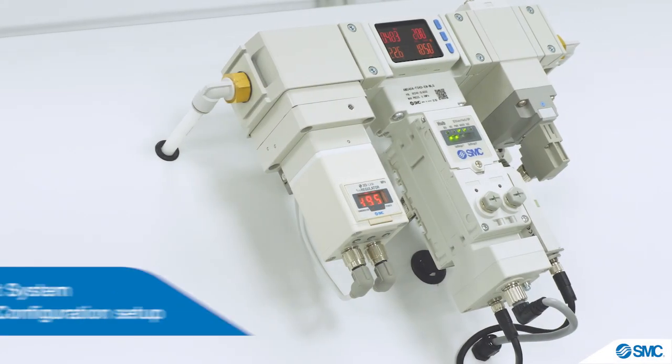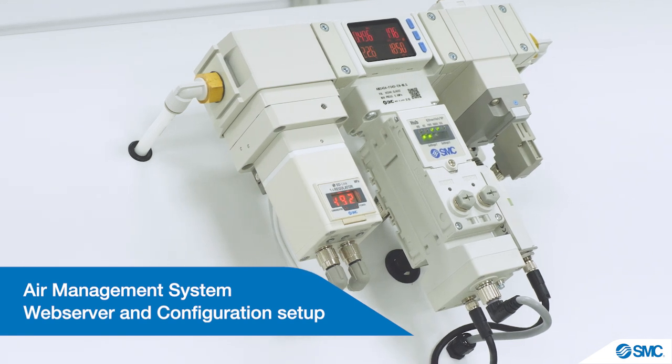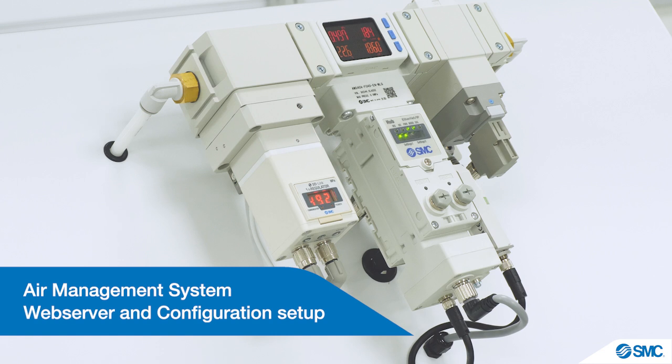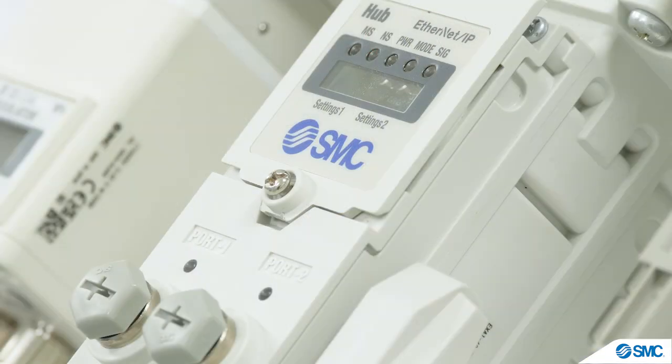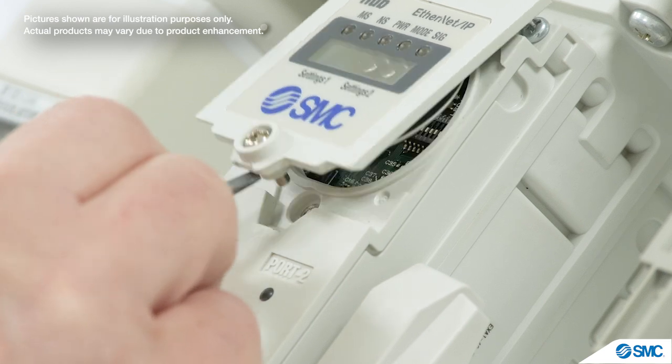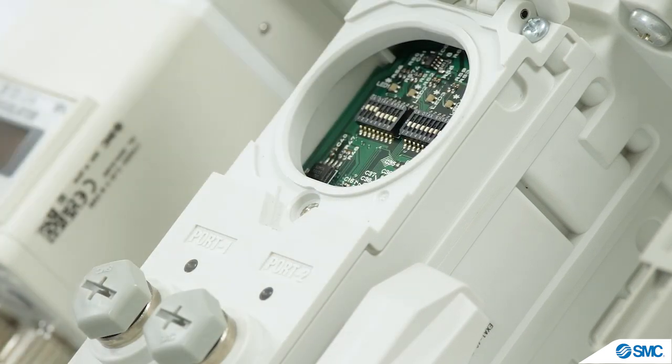This tutorial introduces the Air Management System web server and configuration setup. To set the configuration of the system, we first need to set up the DIP switches. These are found by loosening this screw and lifting up the cover.